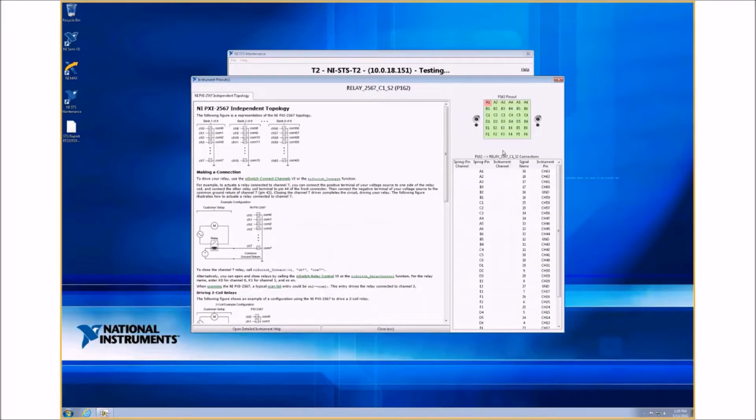So you can pop up this pinout view and it'll show you exactly which pin has been broken or which pin is in question. So there's a couple of things you can do at this point. Obviously the easiest is to replace pogo pins. If that ends up not working, you then replace the cable, and then of course you can go all the way down to the module.